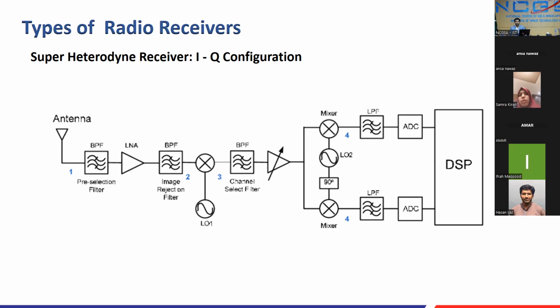Some of the arrangements we make, you may also find implemented on the digital side, because it can easily be implemented on the digital side as well. The purpose of this is image rejection, because when you mix two signals 90 degrees apart in phase on the same frequency, you may reject the image produced for the signal. The significance of that is